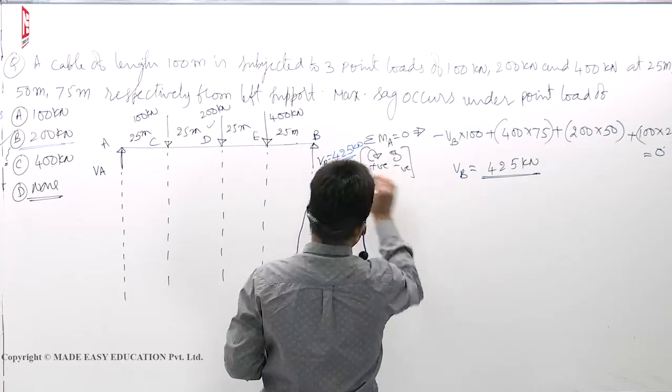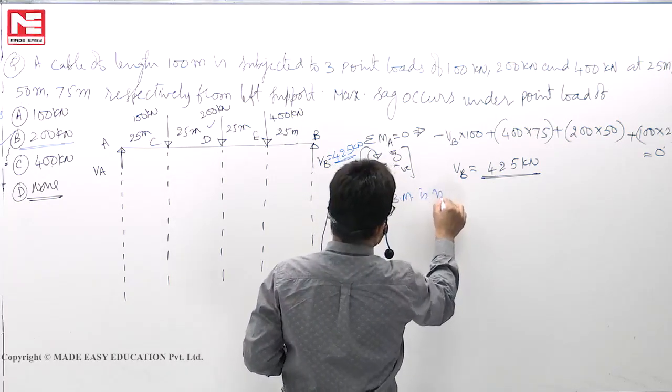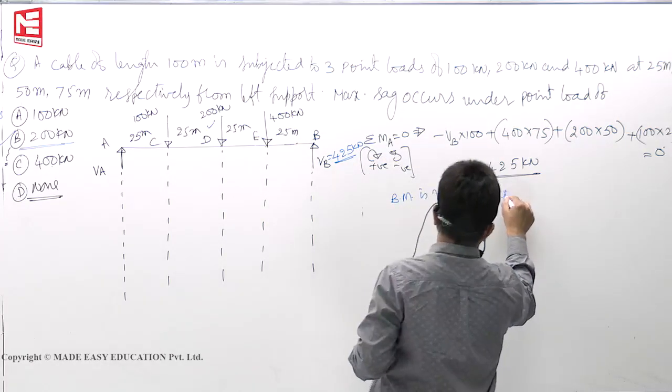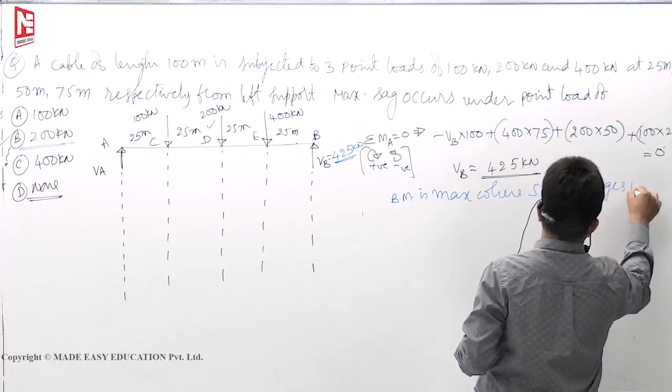Now to find maximum bending moment we will not calculate. Bending moment is maximum where shear force changes its sign.